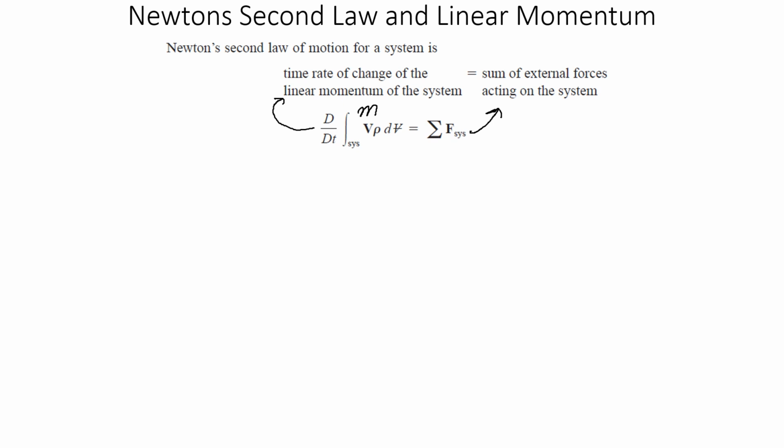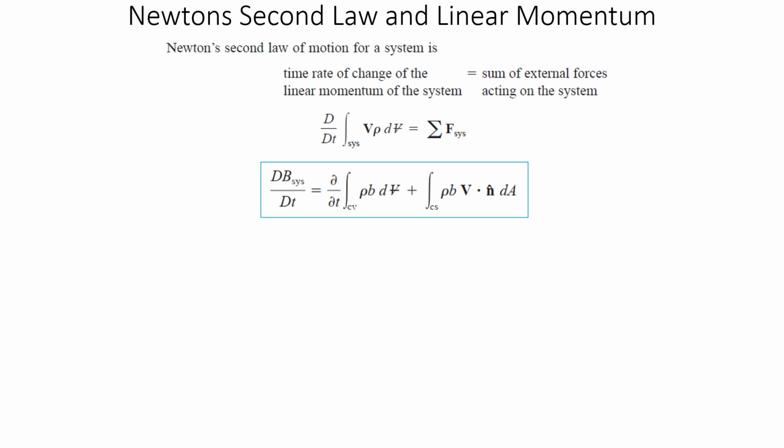So just to be clear about these terms, now moving forward, we get this term, that is our complete Reynolds transport theorem. This term will be replaced by the summation of forces in the system, and this is the partial change of our system inside the controlled volume with respect to time. We will be considering steady cases. So in steady cases, our time rate of change, partial change, will be equated to 0, because we'll be looking at the steady cases only.